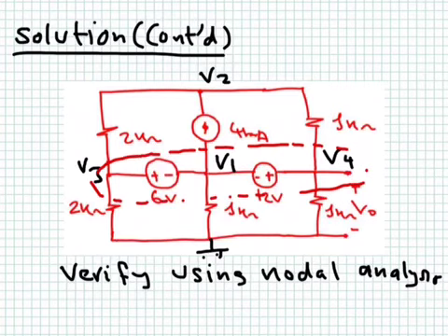I wrote the expression here. So how many currents are flowing out? One current flowing out, second current flowing out, third, fourth, fifth, and sixth. And you can write all these currents in terms of V1 and V2. Because remember, V3 is V1 plus 6, V4 is V1 plus 12. And you have to write KCL here as well. So you obtain 2 equations and 2 unknowns. One equation from the super node for V1, and one equation from this node here. So you have 2 equations, 2 unknowns, and you solve for them.